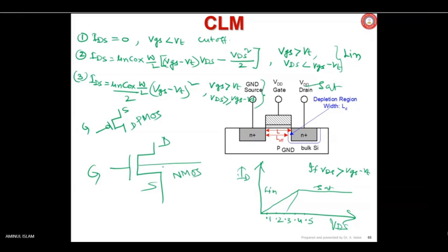Now, if I give some voltage, and its threshold voltage also. For this MOSFET, say the drain is 1 volt, the source is 0.5 volt, the gate is say 1 volt, and the body is grounded. And your threshold voltage Vt of the N MOSFET, I am writing Vtn equals 0.4 volt. Can you tell in which region the MOSFET is operating?